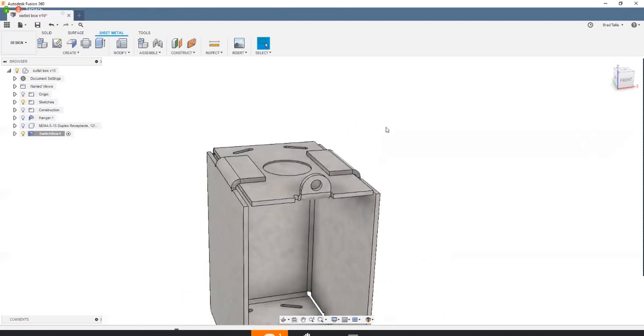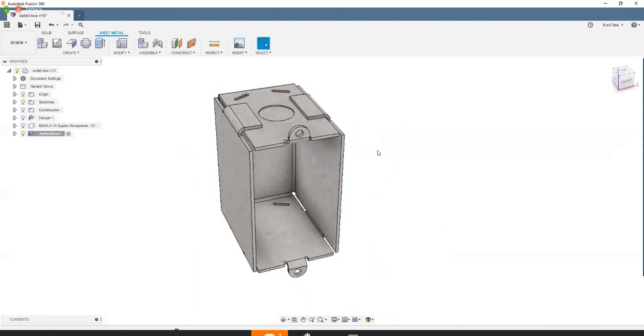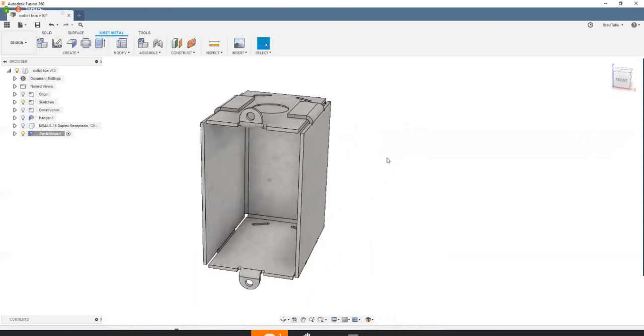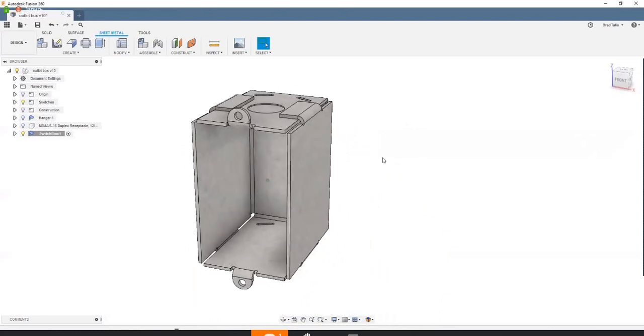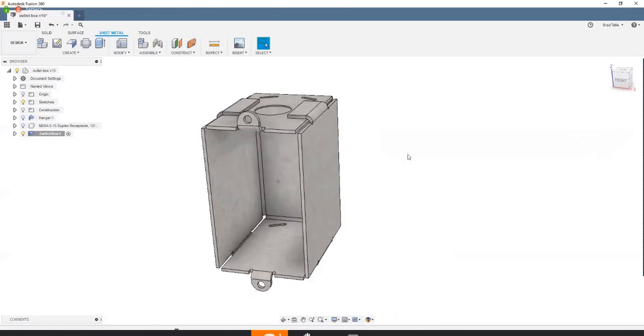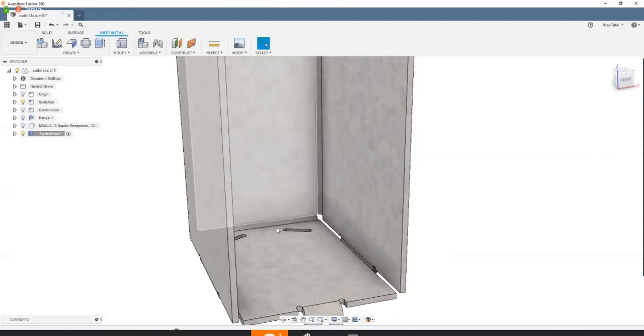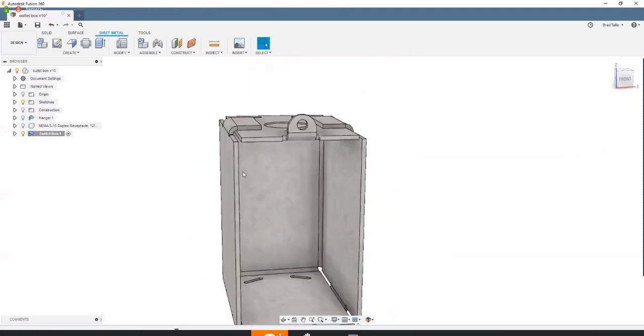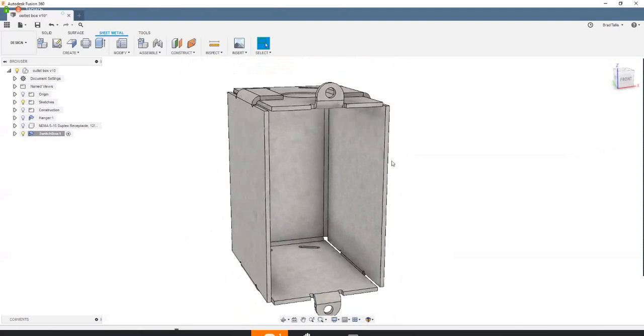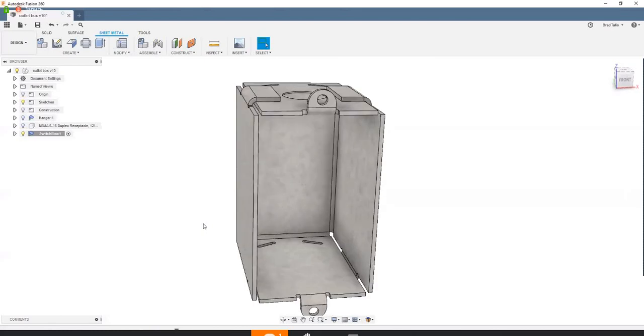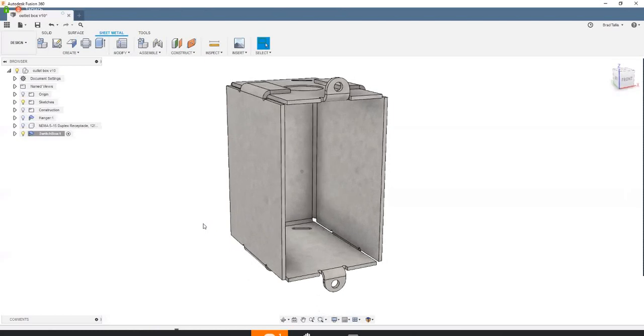Okay. So yeah, we don't have stamps, we don't have punches right now. But you might see some of those down the road. And then Jerome asked a question at the very beginning, how would you create a reinforcement crease on large sheet metal? Same thing, if you want it to unfold, it kind of has to be all the same thickness. So I would probably just create a general note saying, manufacture a 1/4 inch crease or something like that. Or you could model it and see if that worked.